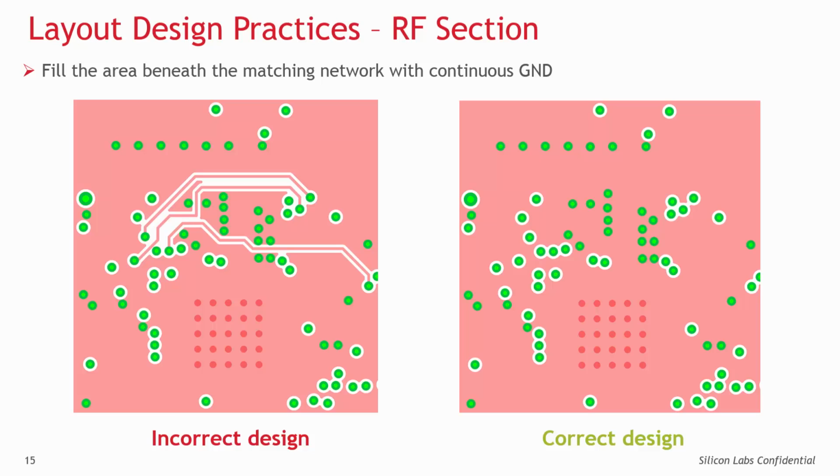Board routing and wiring should not be placed in this region to prevent coupling effects with the matching network. It is also recommended that the GND return path between the GND vias of the TX or RX matching network and the GND vias of the RFIC paddle should not be blocked in any way. The return currents should see a clear, unhindered pathway through the GND plane to the back of the RFIC.